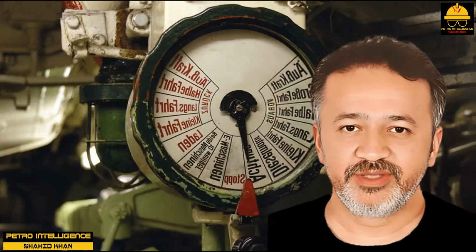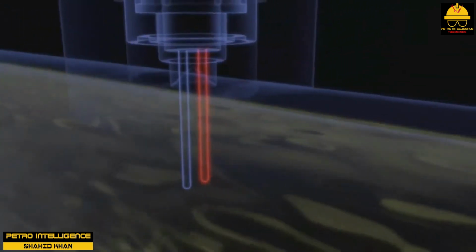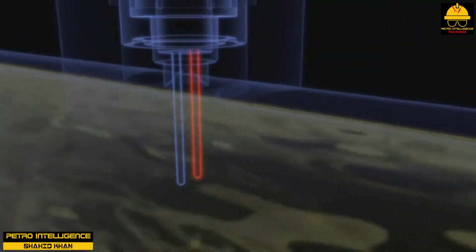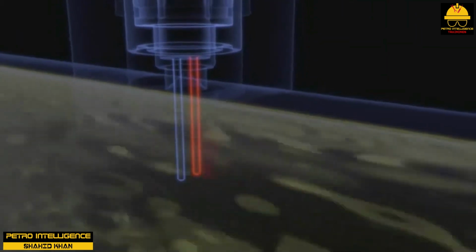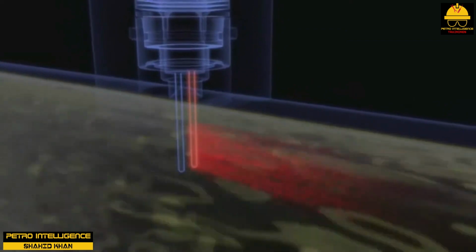Thermal flow meters. Thermal flow meters measure flow rate based on changes in resistance due to changes in temperature. Thermistors are used to measure the change in resistance. Thermal flow meters are sensitive to the thermal conductivity of the fluid and are usually designed for a specific flowing material.